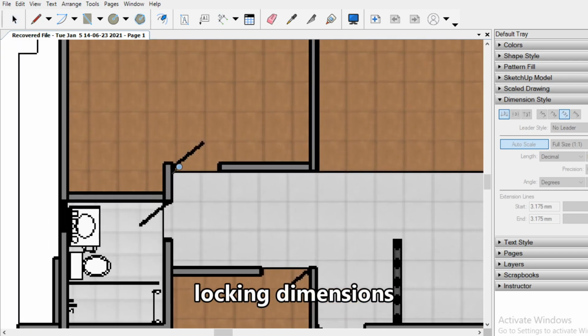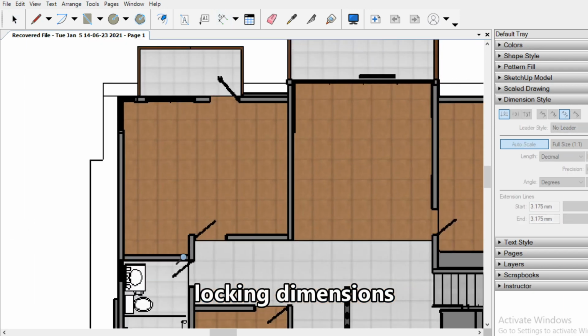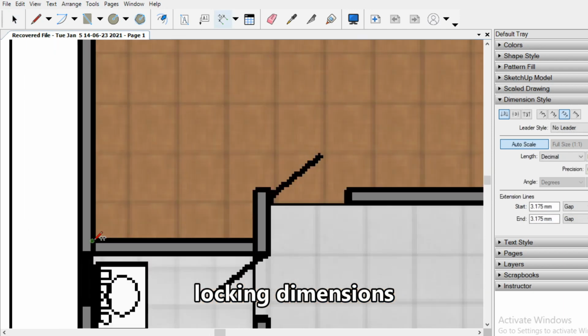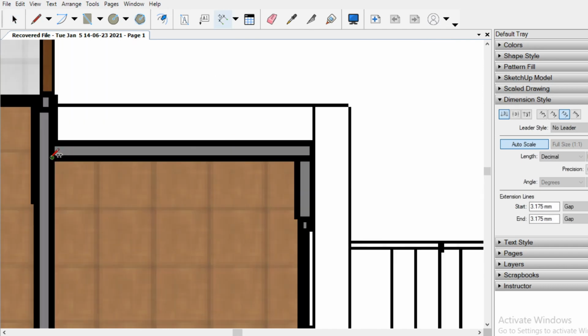If you're having a hard time locking onto the joints, make sure your SketchUp model is neat so that intersections can easily be gotten. This is one reason why I don't like to explode the groups yet, so that it's easier also for the laying of hollow blocks and real construction.